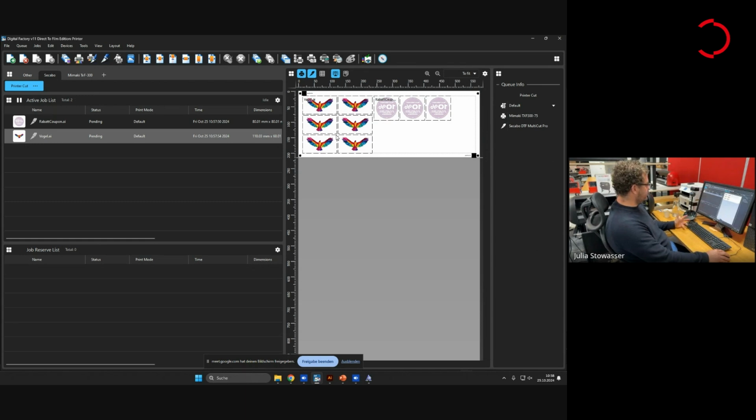This is perfectly possible. You can work that way, but it will create two things. The first thing is it will be much, much slower because the length of each cut is short. Then the total length of cutting is much longer, as it needs to be cut around each logo. And the waste that you create is a lot more complicated because you get this waste web.